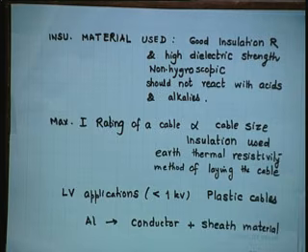The insulating material used should have good insulation resistance and high dielectric strength, non-hygroscopic. Water should not affect it. It should not react with acids and alkalis.